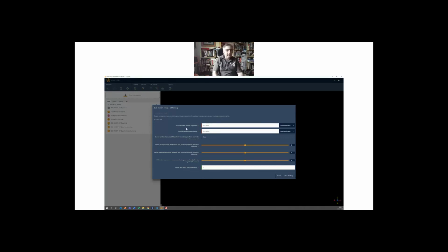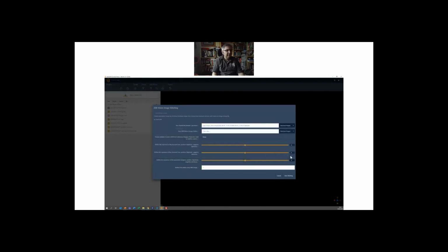Firstly, what we're asking for is the .GeoSLAM. We don't typically use the .GeoSLAM in the stitching workflow. We're just making sure that we're definitely using the right project folder. So we use the .GeoSLAM file just to pick out the project name. And that's why I would just pick from project.